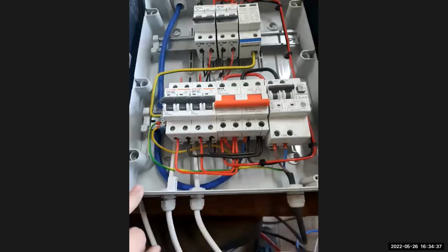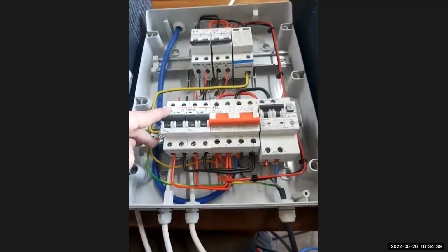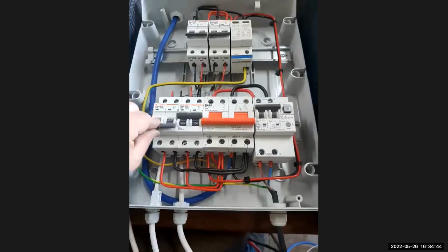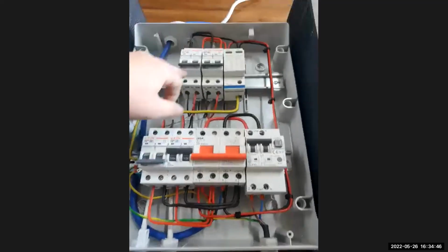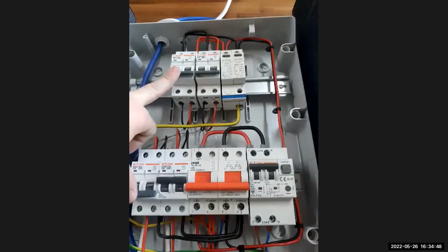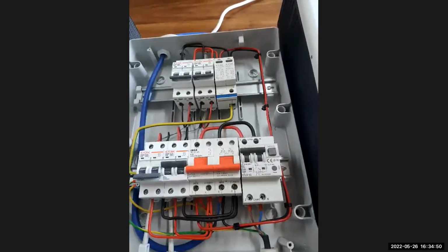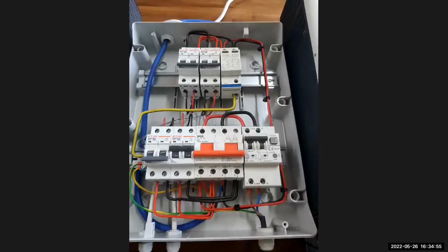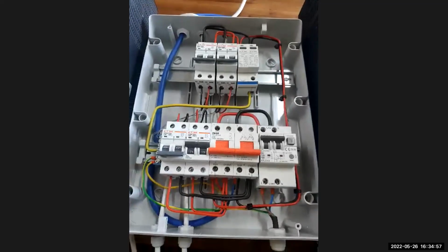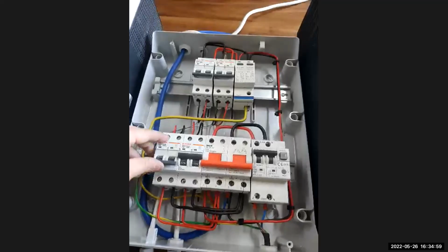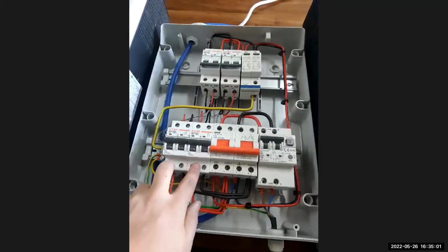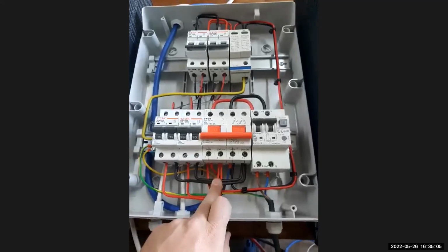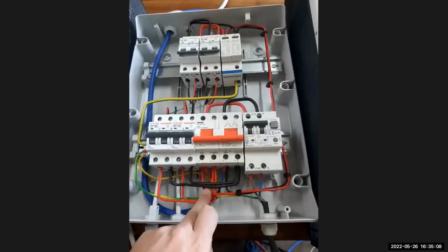The reason why you have output breakers is to disconnect a system. If one inverter breaks and something happens, you can switch one off, and then you can also switch off the input breaker, and this inverter is completely isolated from the rest of your system, and you only go back to adjust the settings for the number of inverters that you have left. So for this system with the two inverters, my output breakers are combined at the bottom of my changeover switch. This is where the paralleling happens.